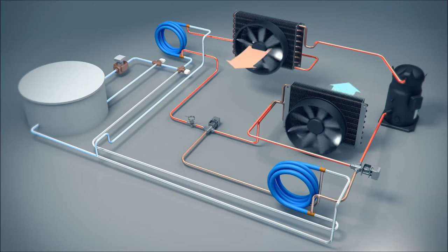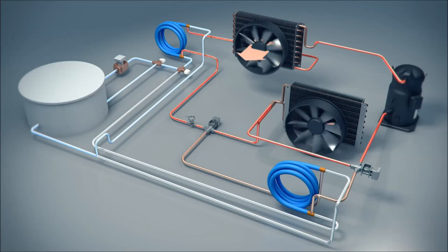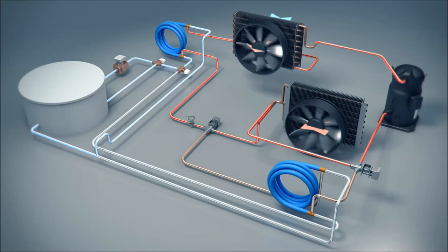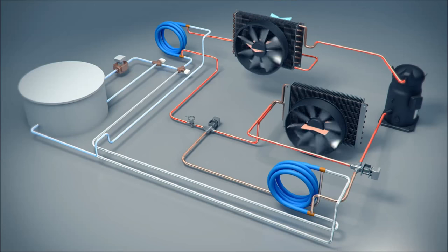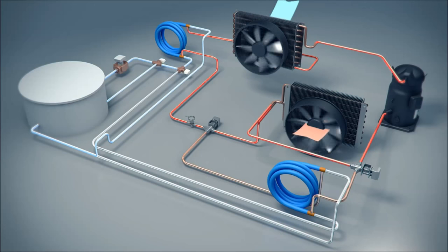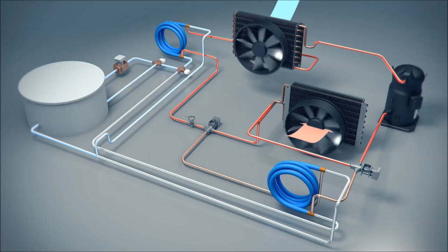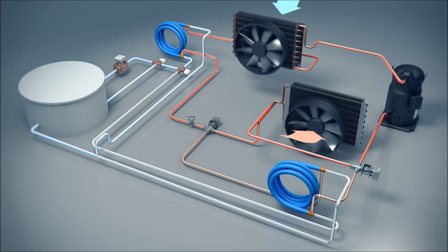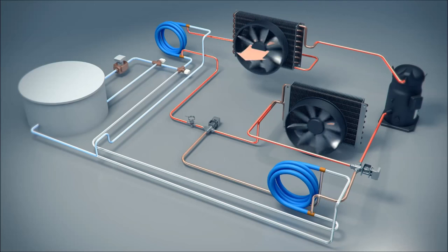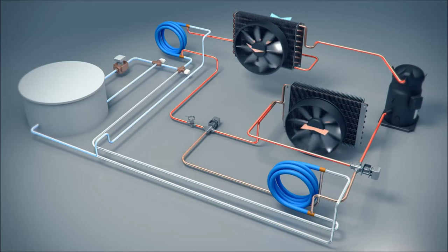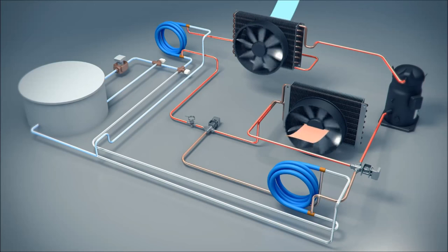The heat exchanger is defined by an interface between a glycol solution and the system refrigerant. Heat is transferred from the hot refrigerant to the low temperature glycol solution, thus reducing the overall temperature of the refrigerant significantly. The refrigerant exits the heat exchanger and continues through the remaining components as found in the standard refrigeration cycle, as shown in the first segment.